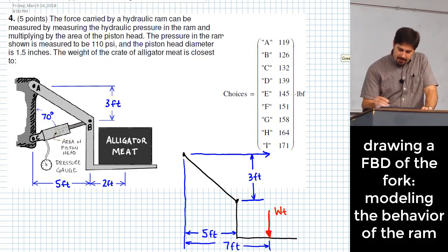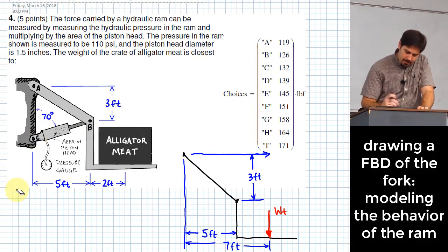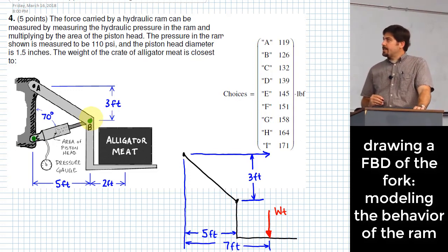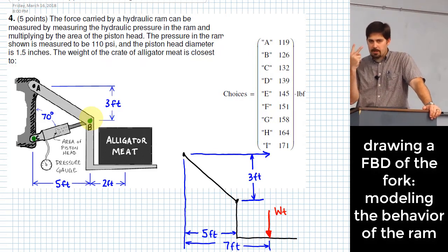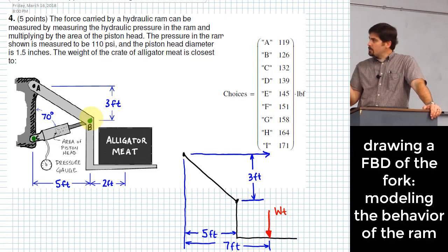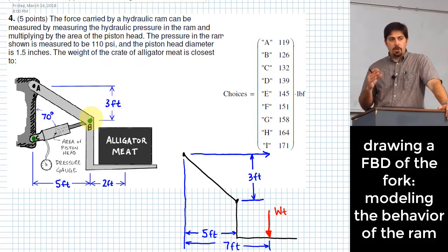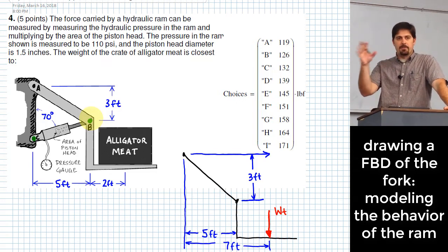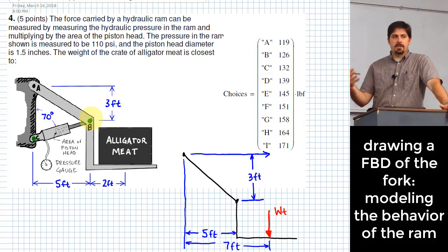One thing I'll say about it is this body connects from one point to the other. So it connects from this point right here to this point right here. It is connected only at 2 locations, and it's connected with frictionless pins. So if we have those conditions met, and I guess a third condition that no other forces are acting on it either. No outside forces come in and act on it, which means that we'd have to do things like neglect self-weight and that kind of thing.